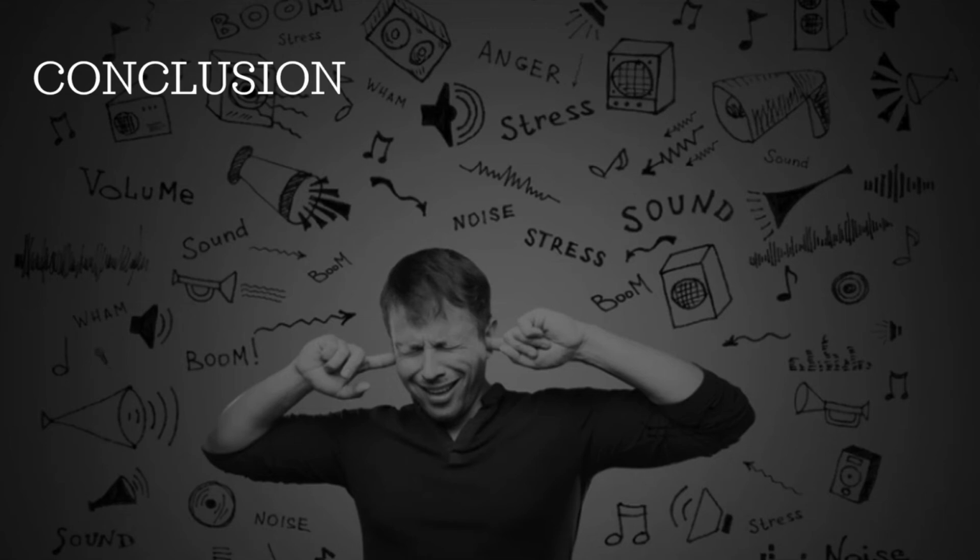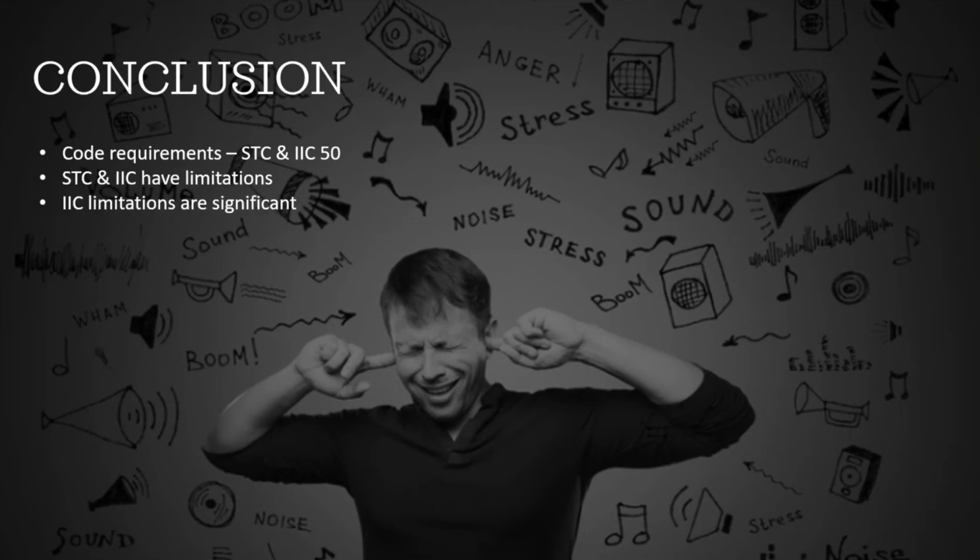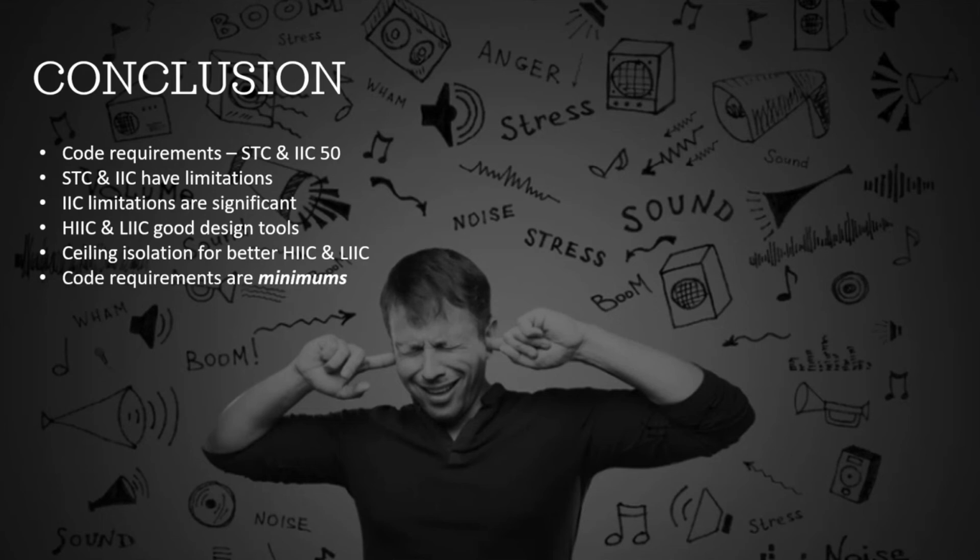All right, so in conclusion, code requirements for multifamily, right? STC and IIC 50, those are minimums. Those ratings have their limitations. IIC limitations really are significant, I think. The HIIC and the LIIC are good design tools that help address some of those limitations of the IIC rating. Ceiling isolation can really help with better HIIC and LIIC ratings. Flooring and underlayment really does more for HIIC predominantly. Again, the code requirements are minimums.